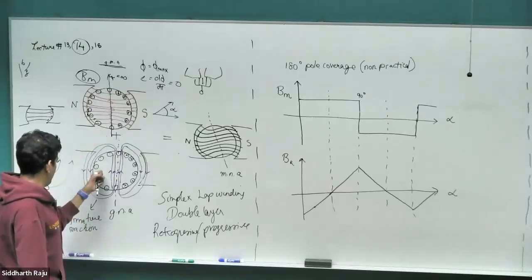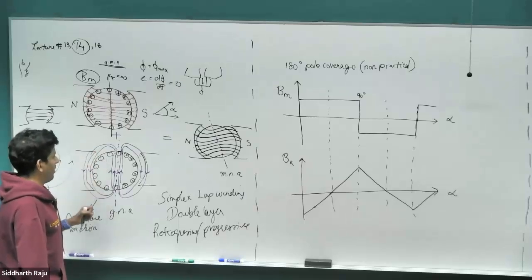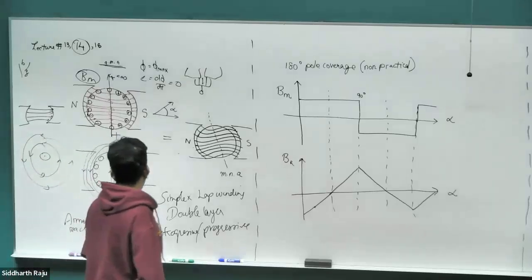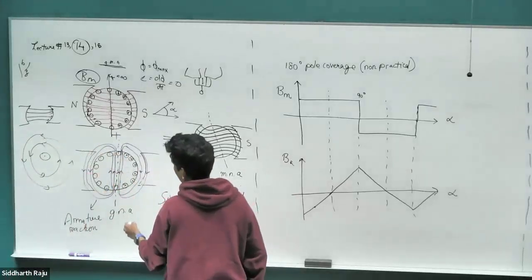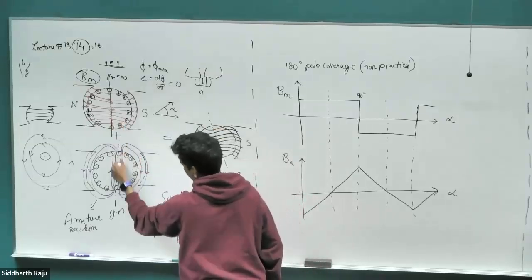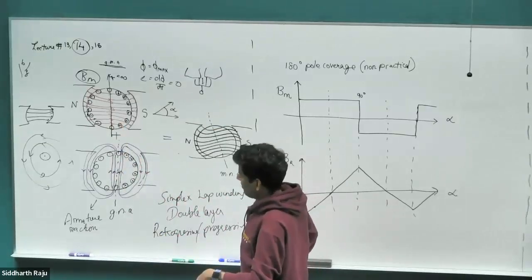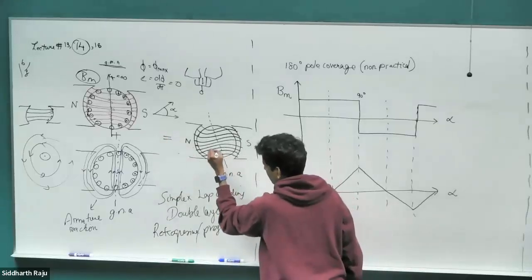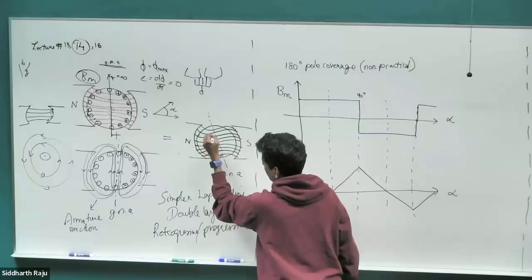But what happens is, due to the magnetic field created by these current carrying conductors on the rotor armature structure, there's going to be an additional magnetic field that's created. So the net magnetic field experienced by these conductors will be the sum of these two magnetic fields. Right? So you can do some FEM modeling and sum these up. And this is what the structure of the magnetic field lines that come out of it would look like.